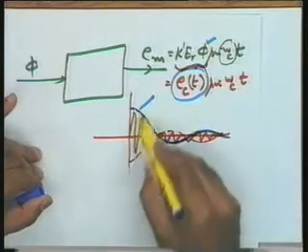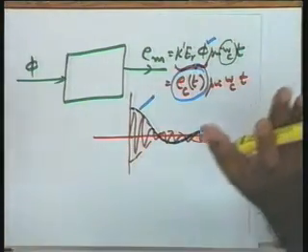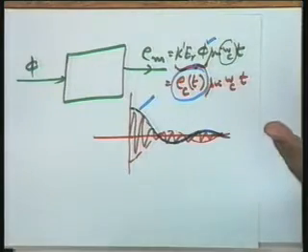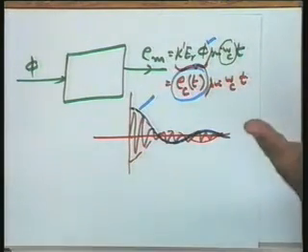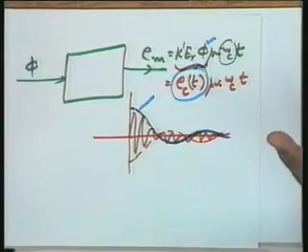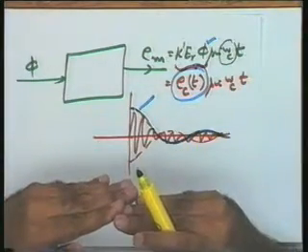The carrier does not carry any information about the control action; it is there just because the device is operating at a frequency omega_c. So as far as the transfer function model is concerned, I may be worried only about the envelope Ec, and I should not concern myself with the total output Em, which is a modulated signal coming from the synchro error detector.